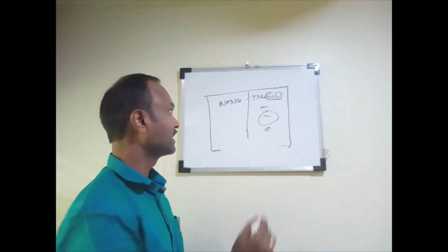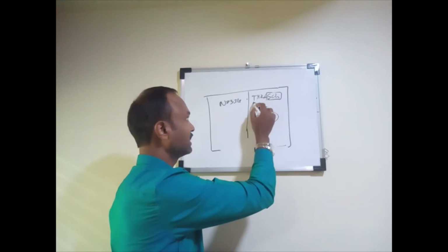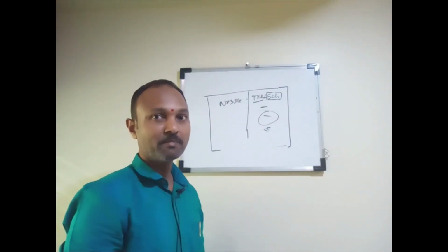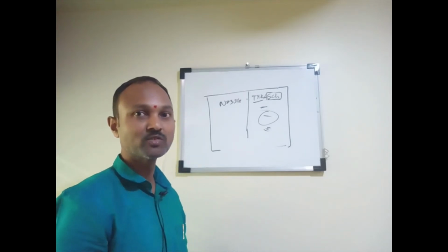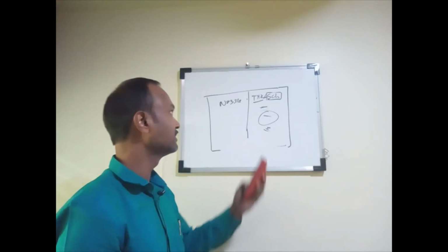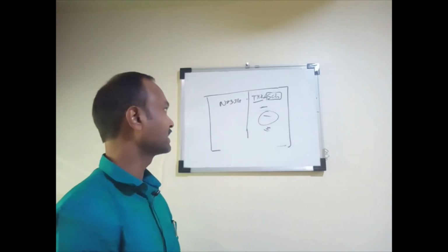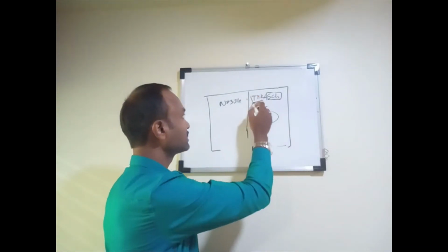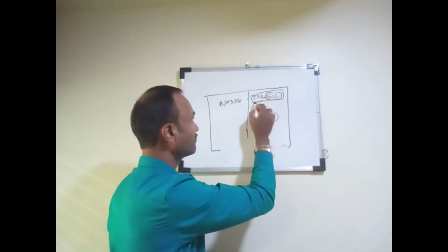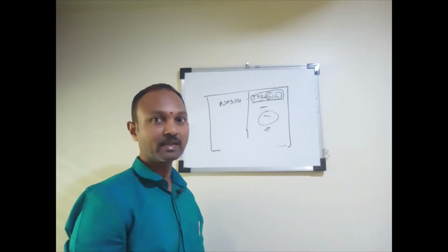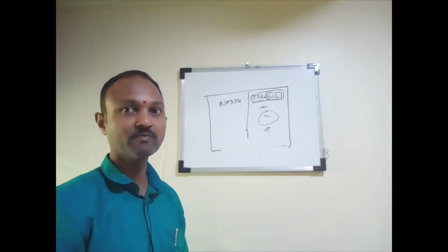So this schedule we will take, and if we take this thickness, normally if you make the nozzles from plates, if the nozzle size is very large, we will make it with the thickness of plates. So in that case we'll take that thickness. So we have to mention either this thickness, or the schedule of the nozzle we are taking for this vessel.